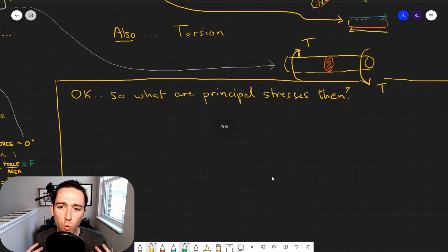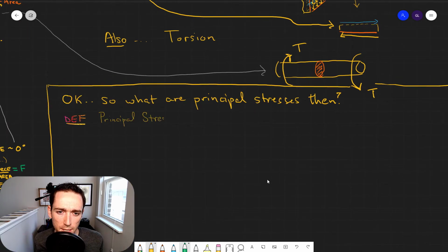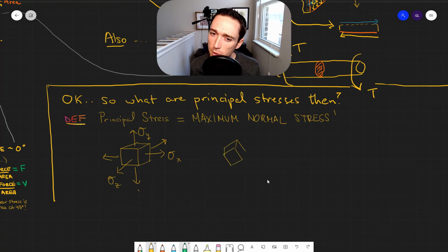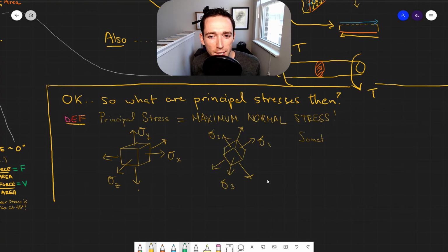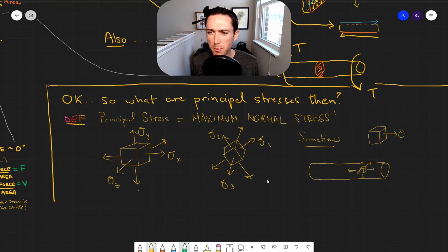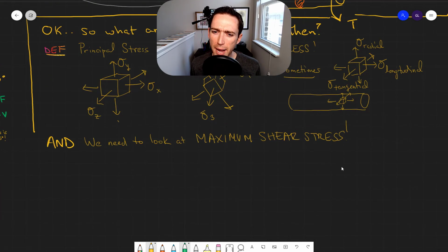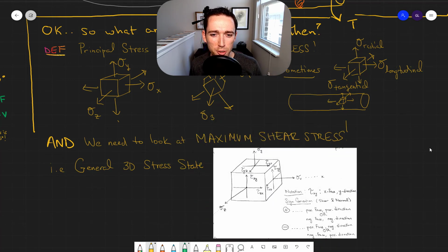Okay, so here we are. What's a principal stress then? Principal stress is just the maximum normal stress. That's it. Because we have XYZ that we're often looking at, but if we're oriented in some other direction, we might go 1, 2, 3. And if we have a special geometry like, say, a cylinder, we might call it longitudinal and tangential and radial. Now, after we look at normal, we also need to look at maximum shear. Once we look at normal and shear, what have we got? We've got our general three-dimensional stress state.